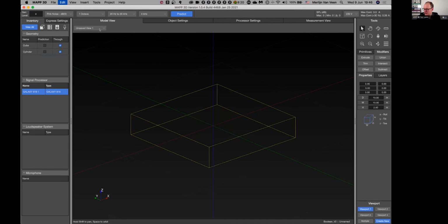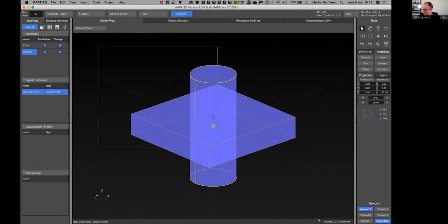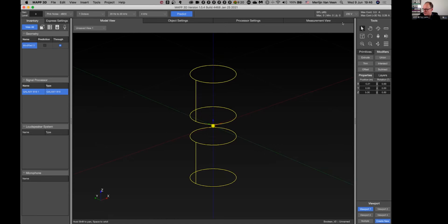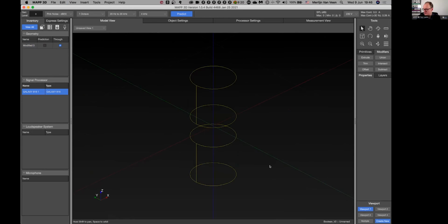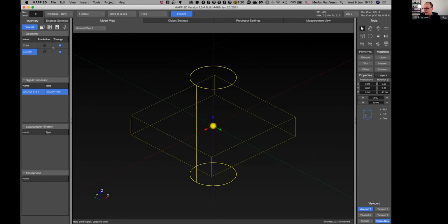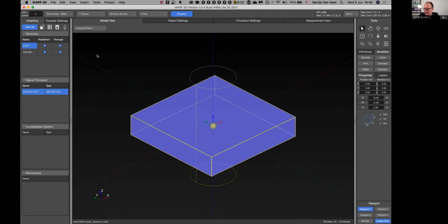And finally, there's a third option that we can use, which is, let's activate these guys once more to give them mass, so to speak. There is the subtract. Now, what subtract requires you to do is literally subtract one volume from the other. So if I now were to select the cube, then it's going to remove its volume from the cylinder, and what is left over is a cylinder which basically now exists of two pieces. Whereas if we subtract the other from the one, then it should not come as a surprise that we'll end up having a hole in our cube.